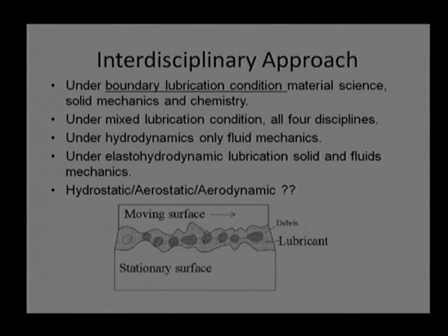case. If there are some dirt particles passing in the liquid, they can occupy the space between surfaces, and then they can reduce the film thickness, or they can effectively increase the surface roughness. So, every hydrodynamic mechanism can be shifted to mixed lubrication depending on the operating condition. So, in real sense, we need to account for all four disciplines whenever we want to attack any tribology problem.